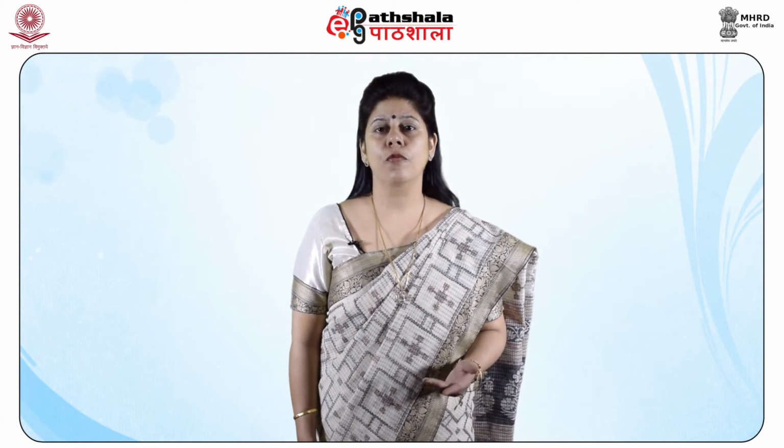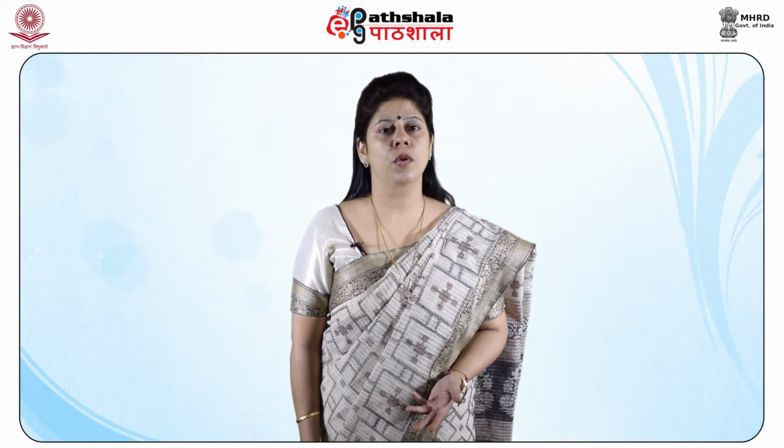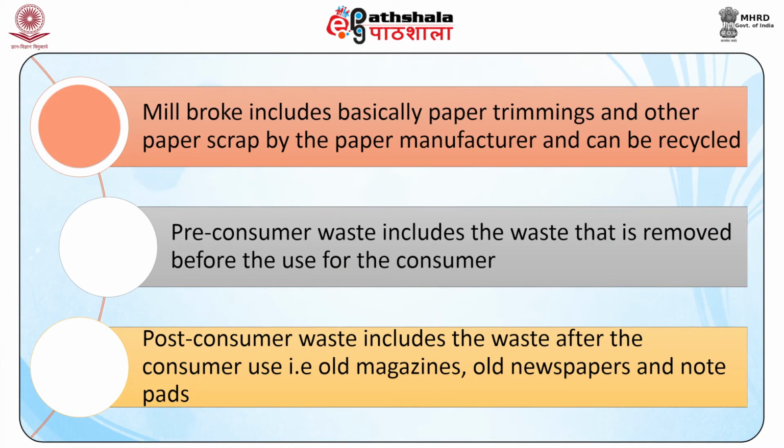There are three classes of paper waste, that is the mill broke, pre-consumer waste and post-consumer waste, which can be used as a feedstock for producing recycled paper. First one, mill broke, includes basically paper trimming and other paper scrap from the paper manufacturer and can be recycled. Next, pre-consumer waste includes the waste that is removed before use by the consumer. Next, post-consumer waste includes the waste after consumer use, that is old magazines, old newspapers and notepads.